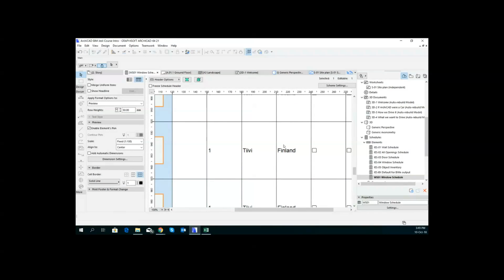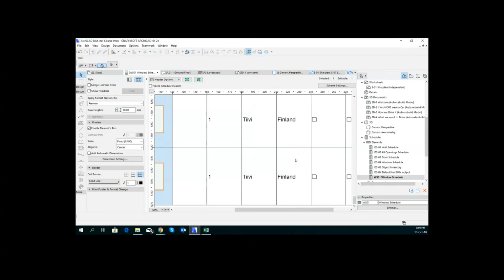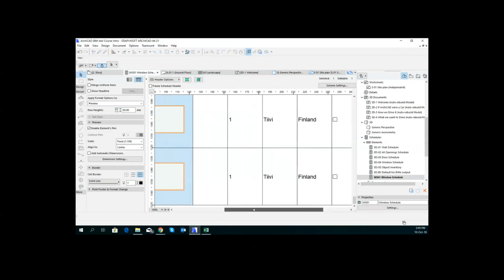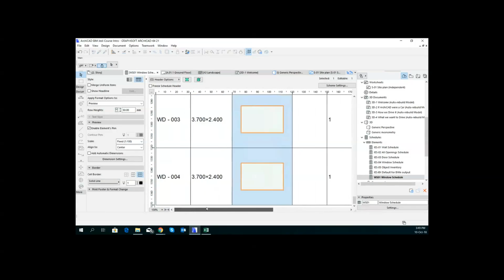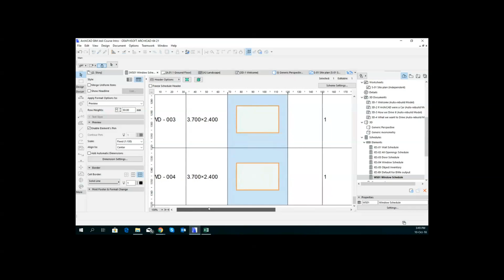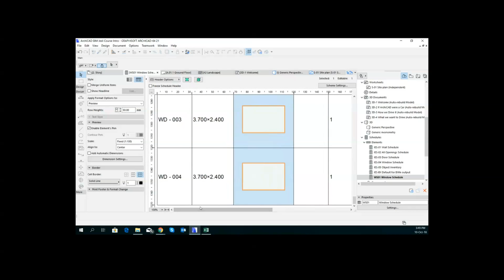Yeah. So it's where we've got these hospitals with lots of projects. As long as you know where the doors are and all the windows, you can do a lot of this quickly and easily in Excel rather than opening every window and going and changing the data and then closing it and going to the next one. So I've just done all, whatever, 20 odd windows there at the touch of a few buttons and saved a few times, and now I can go and have a beer while everyone else is doing their work.